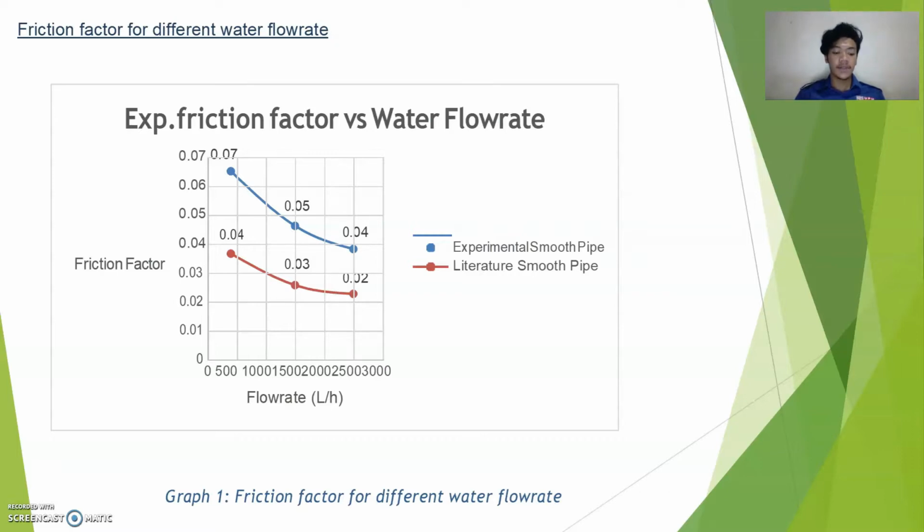Regarding the Reynolds number, from a physical standpoint, it is the ratio of kinetic force to viscous force. Consider the limiting cases of zero and infinite Reynolds number. Near zero, there is no momentum and all forces are viscous. Near infinity, viscous forces are negligible and momentum forces govern. So the friction factor will decrease as the flow rate increases.